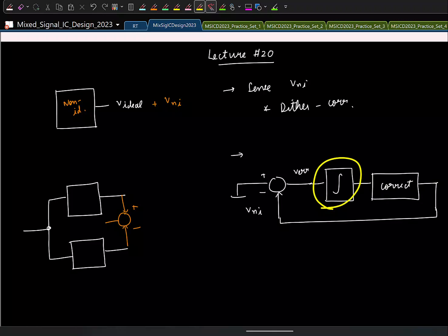This essentially is a negative feedback system wherein you exploit the fact that if you have an integrator, the DC at the input of the integrator, what will this be? It will exactly be 0. Okay. See, I'm sure you have learned about gradient descent, LMS in detail in other signal processing and machine learning courses, but I want you to appreciate the fact that all of this gradient descent and LMS business are based on this negative feedback principle. Right? That's the underlying thing, and that's what makes those things work.